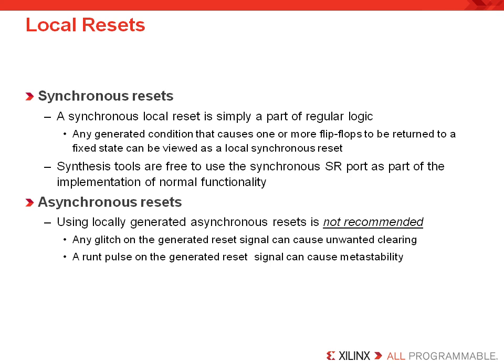Now, synthesis tools are then free to use the synchronous set and reset port as part of the implementation of the normal functionality, or likewise, they could even map it to the lookup table input. Asynchronous resets, though, using locally generated asynchronous resets is simply not recommended. Any glitch on the generated reset signal can cause unwanted clearing. A runt pulse on the generated reset signal can cause metastability as well. And in addition, these cannot be mapped to LUT inputs, so they're rather restrictive and their use is not recommended.